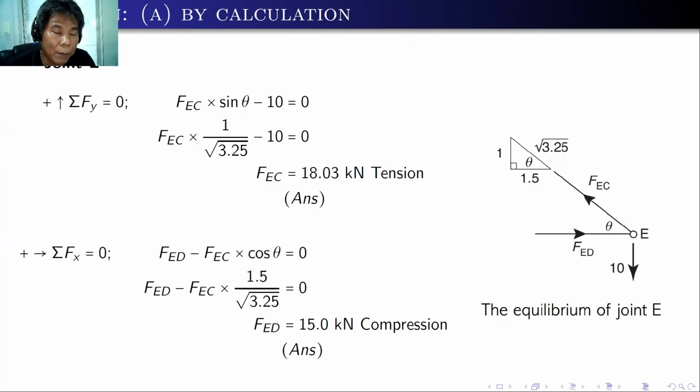So here we will apply the two equilibrium equations, and it's easier if we compute first the vertical forces because there is only one unknown. Of course, you can always use summation forces x and then y, but there will be two unknowns in two equations, and most likely you will commit errors if you do that. But you should look for possible equations that have only one unknown.